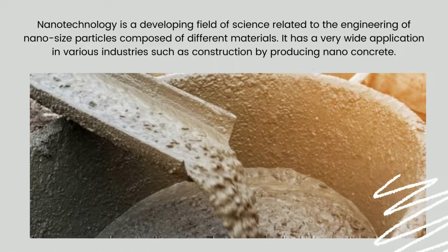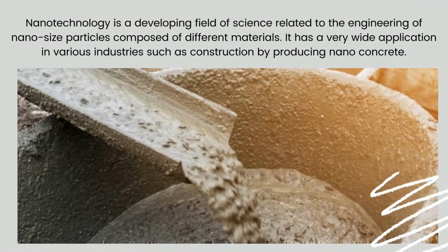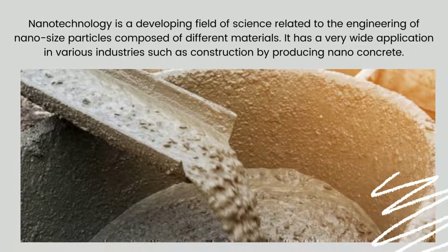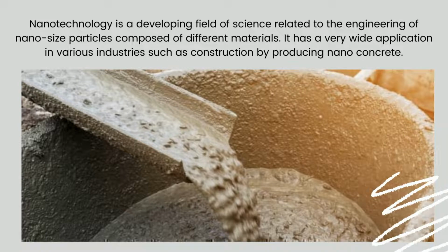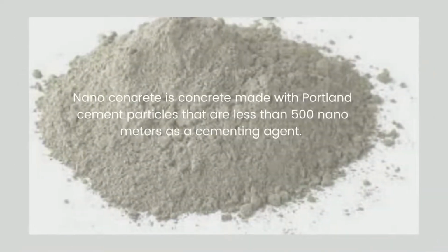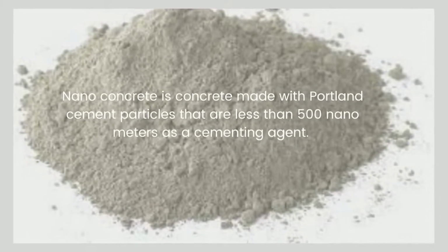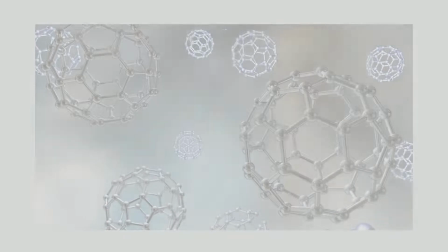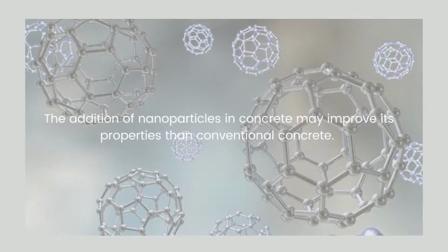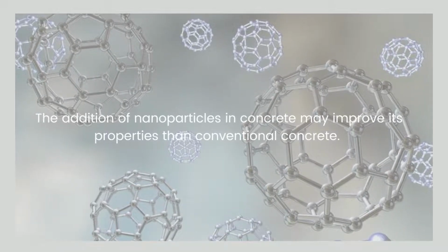Nanotechnology is a developing field of science related to the engineering of nano-sized particles composed of different materials. It has a very wide application in various industries such as construction by producing nanoconcrete. Nanoconcrete is concrete made with Portland cement particles that are less than 500 nanometers as a cementing agent. The addition of nanoparticles in concrete may improve its properties compared to conventional concrete.